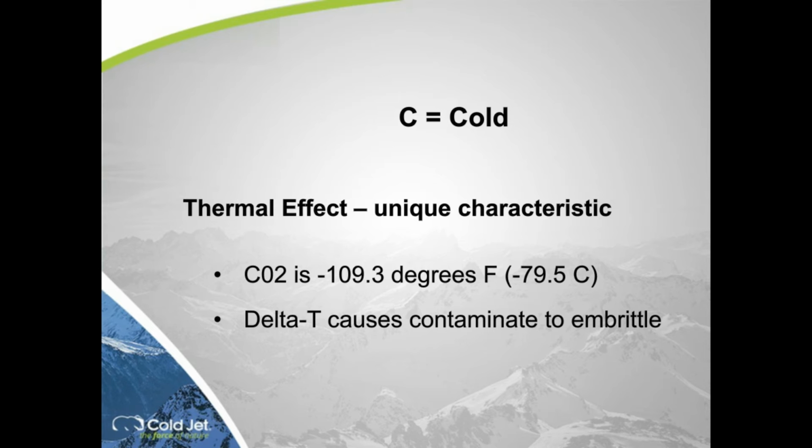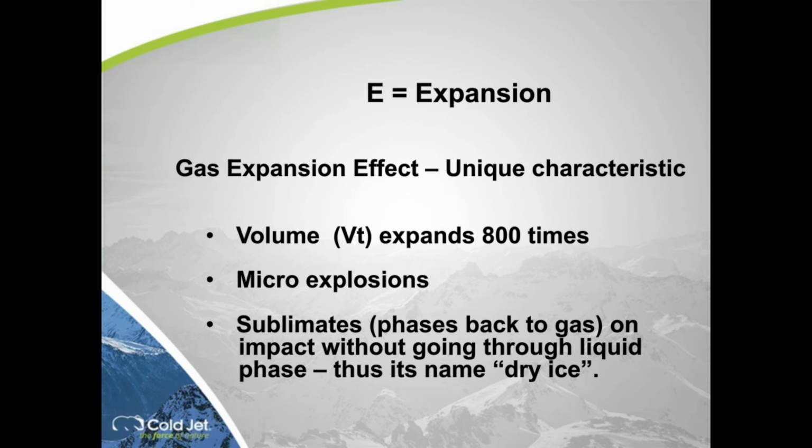The last effect that comes into play, after I've cracked the contaminant with some kinetic energy and embrittled it instantly with the cold: on impact, that solid CO2 will phase to a gas. It's going to volumetrically expand, depending on where you are, at sea level, about 800 times its size.